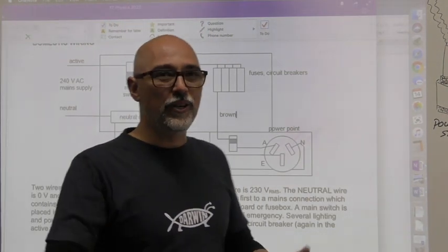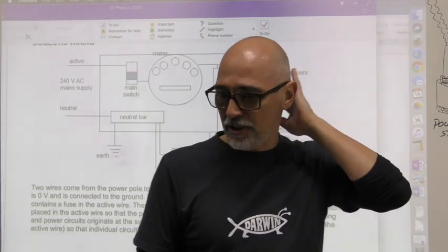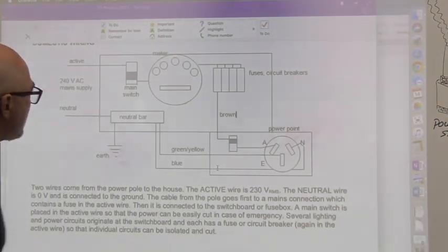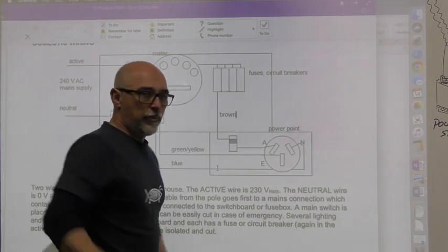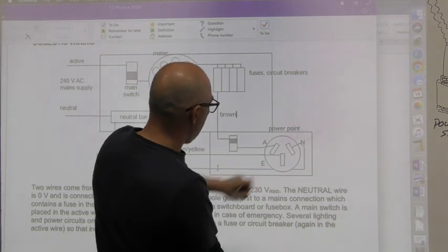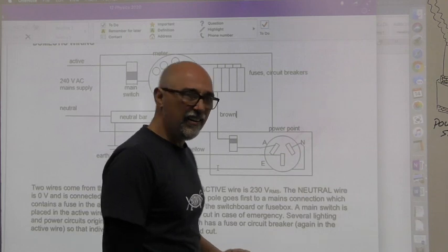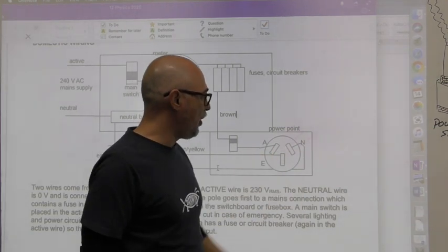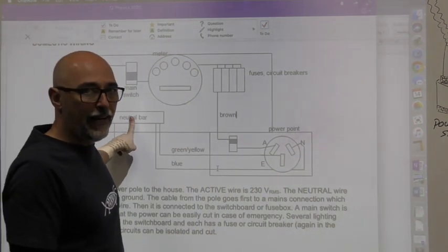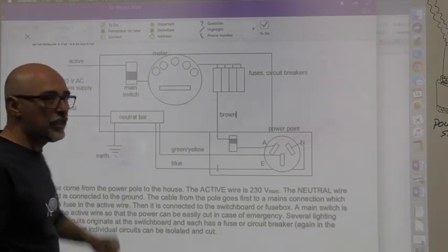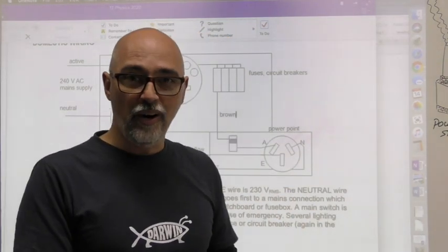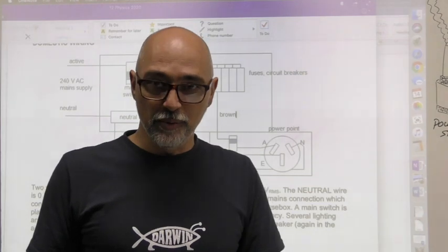Okay, and like I said, you should watch some videos. There's some great little animations and things that show exactly how they work. They're very clever, I must say. Anyway, now, notice, after your fuses, which protect your property, you'll see that in your plug, there'll be an active terminal and a neutral and an earth. Notice that both the neutral and the earth are attached to a metal bar somewhere that is attached to the earth. And when we get back together, remind me to do this, I will show you where the earth wire that connects every power point in the school actually goes.